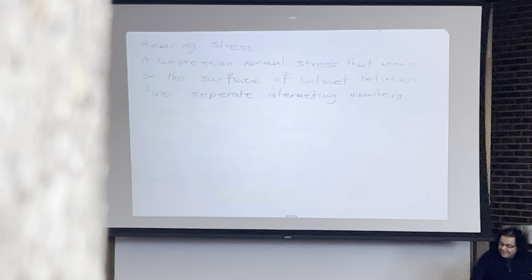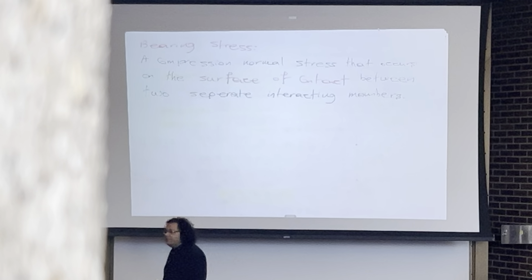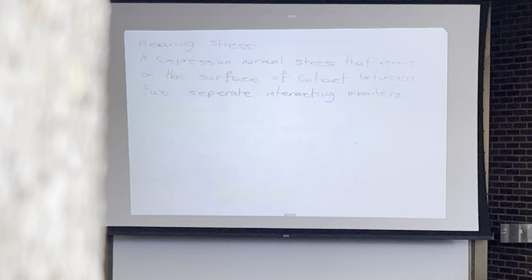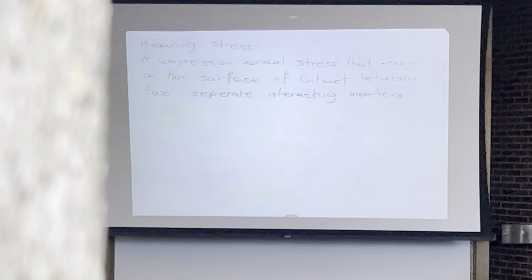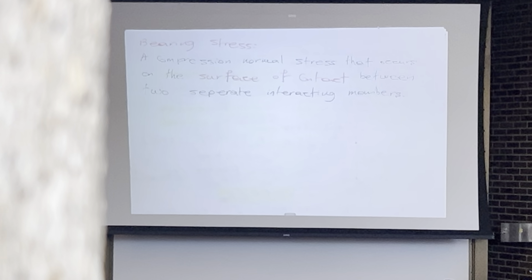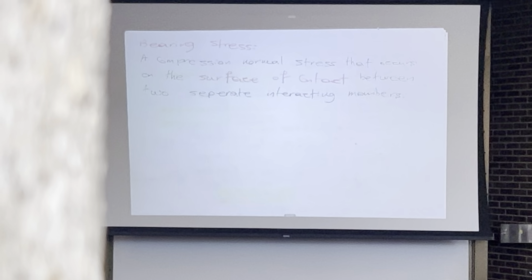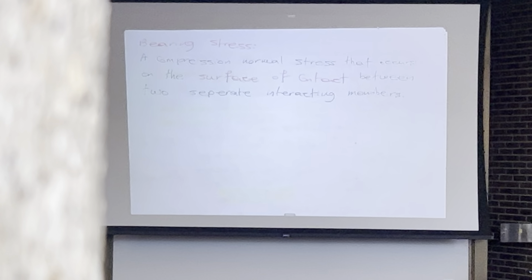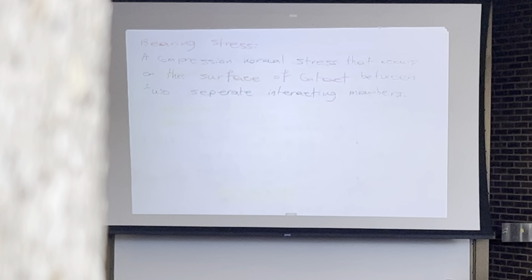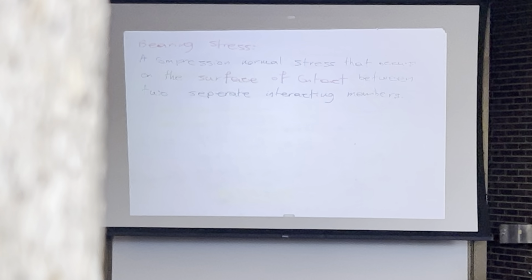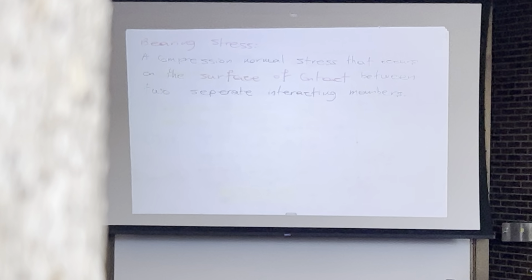So I was saying that the normal and shear stress, when we define them, they actually occur within the material. This was the reason that we defined this concept. It's the intensity of internal forces. So in all the problems that we have solved so far, we first calculate an internal force, internal load, internal shear force, internal normal force, and then calculate the stress. This is the actual meaning of stress.